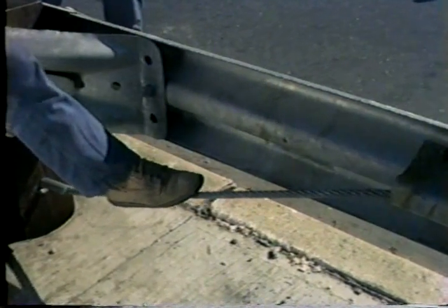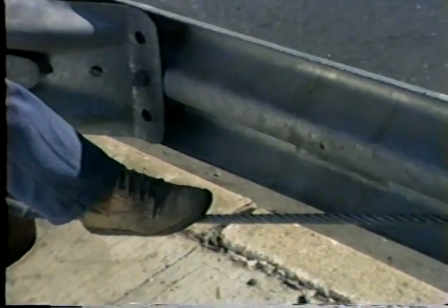A steel insert is used through the drilled hole to keep the cable from tearing the wood post. The cable must be kept tight. 3/4 of an inch of deflection is acceptable. For steel posts, the cable passes through the first post above the slip base. The plate extends down to the bottom of the lower stub plate so that the slip base is not activated by cable tensioning when it's impacted downstream from the end.